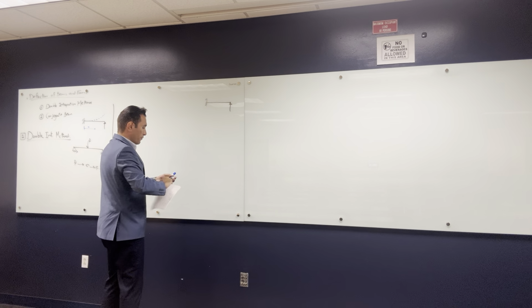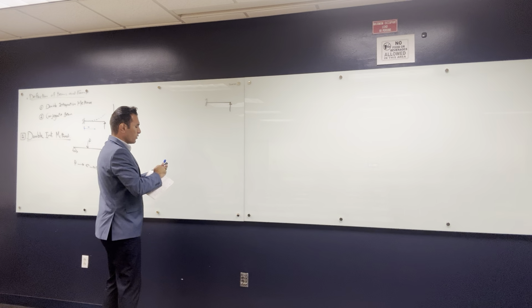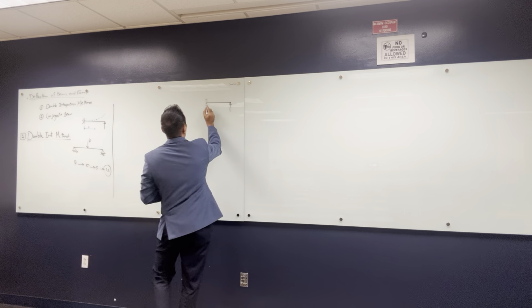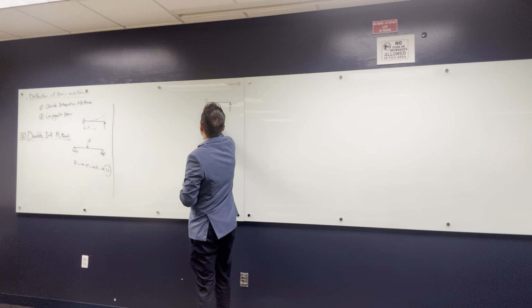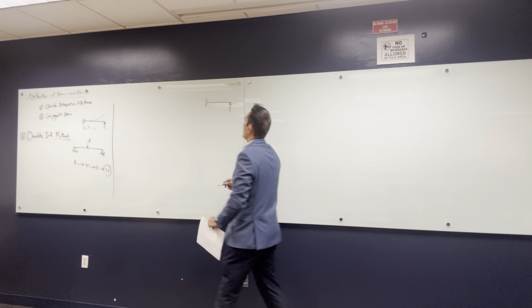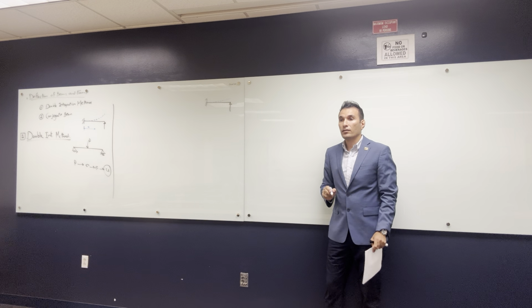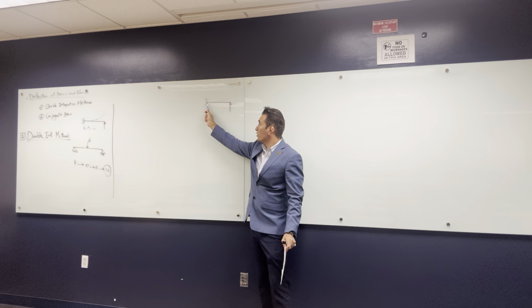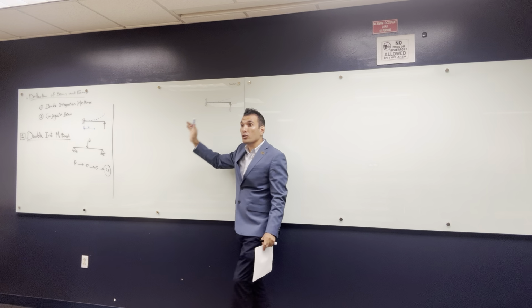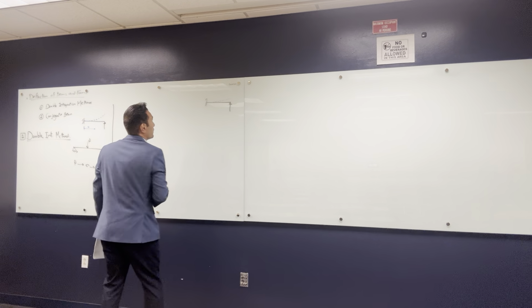This beam, we know how the deflection looks like. We know there's a fixation. The fixation doesn't allow deflection. This is how the deflected shape looks like for a cantilever. What is the amount of deflection here? 0. What is the amount of slope? 0. So slope and deflection are equal to 0.